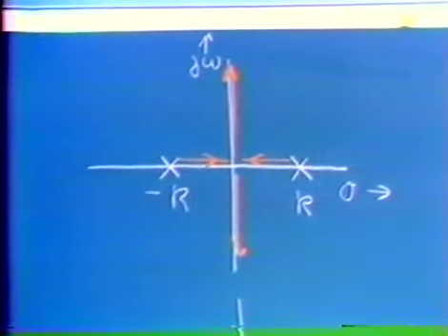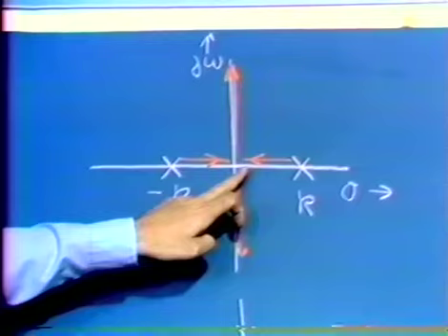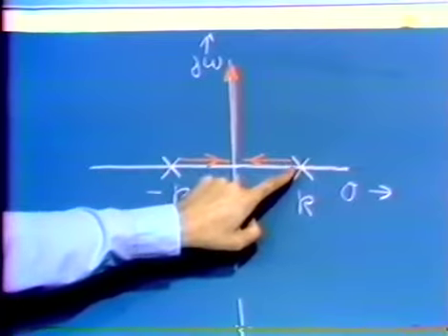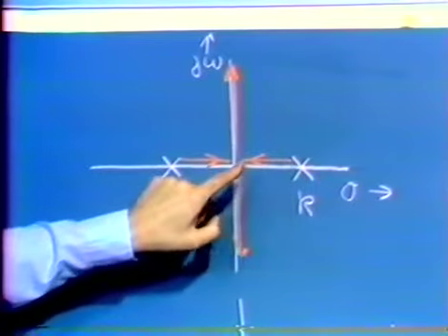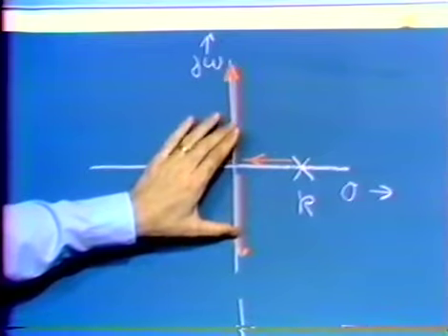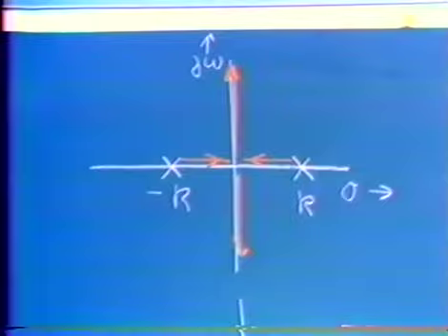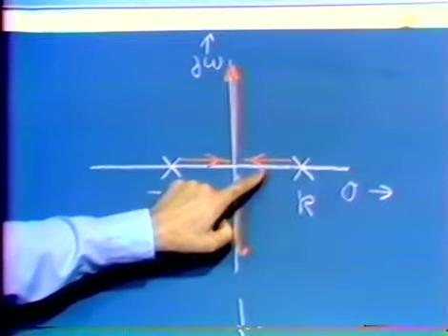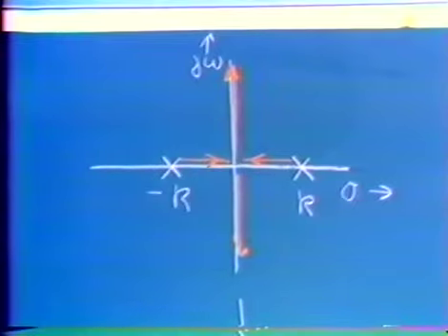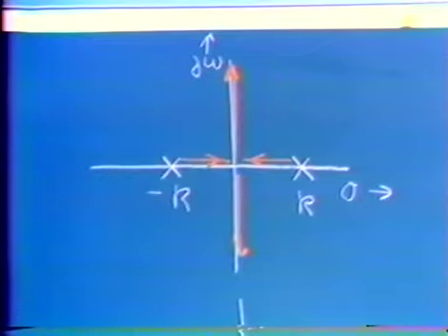along the imaginary axis. So as we increase the gain of our amplifier A, what would happen is that one pole, the one that's giving us the difficulty, would move from its position in the right half plane, finally reaching the imaginary axis. However, as we further increase gain, we then get a complex conjugate pole pair on the imaginary axis. And the implication of this is that while we would have lost the exponentially growing response, we'd end up with an oscillator. Once we have sufficient A to get the closed loop poles out on the imaginary axis, the system describes an oscillator.